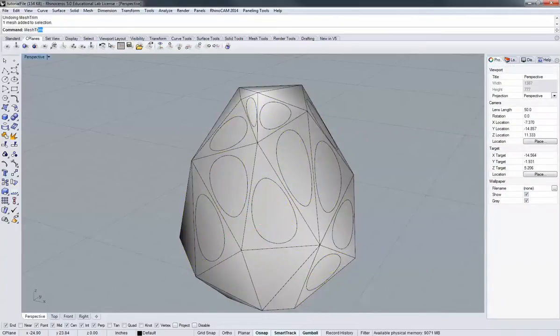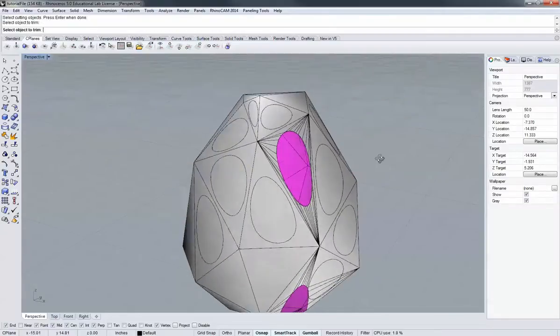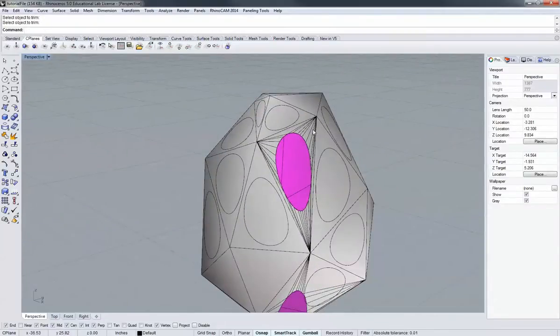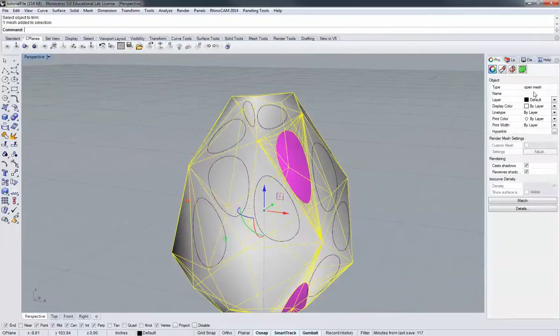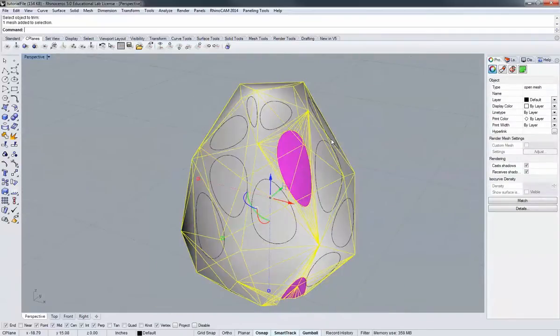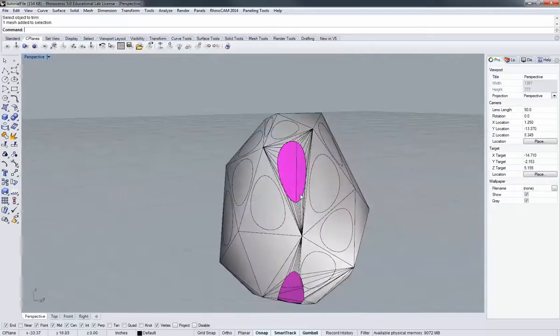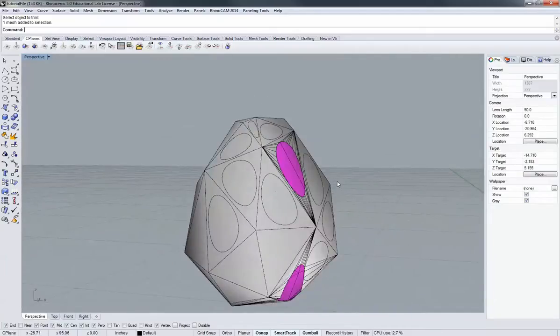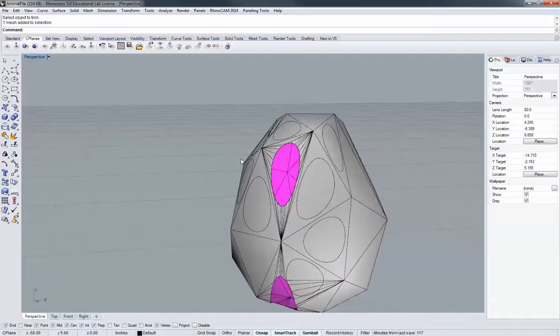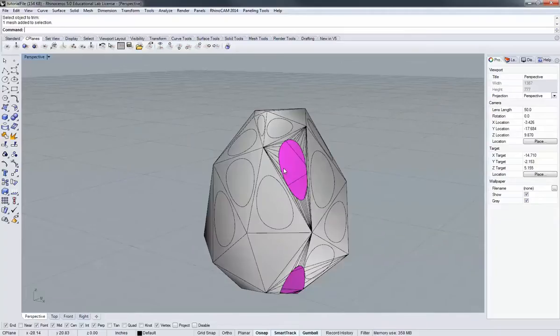But if we mesh trim even a single opening, suddenly it's an open mesh, which would present a problem for 3D printing. So if this is done, you'd have to work with a second inner shell, most likely, that you would then weld or join the faces or polygons together to create a volume, or really a shelled volume.